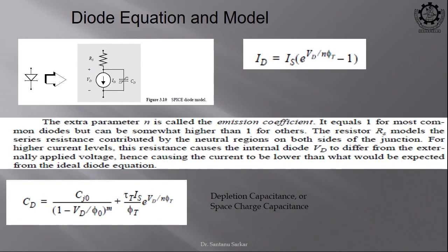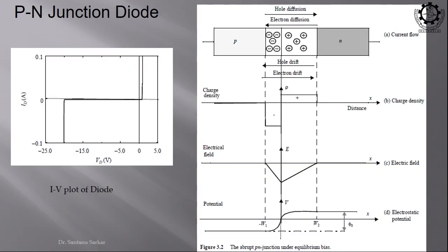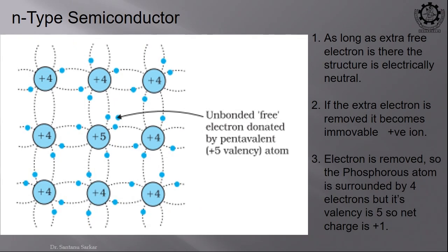Okay. So, sometimes what happens, in this diode junction, in reverse bias also, you can see that this is a space charge region, right. There are no free carriers here, only these are what? These are immovable ions, right. If you see this structure, this is your atom, right. If you remove this free electron, it becomes an ion, and as they are heavy, they cannot move.